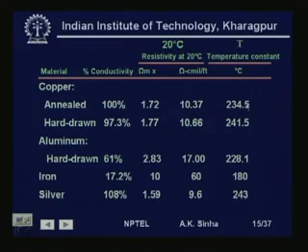As I said, this table shows the temperature constant values. If we look at this table, which also provides the conductivity, annealed copper has been put as 100% conductivity. Then the hard drawn aluminum, which is used for conductors, has 61% conductivity as compared to annealed copper. For finding out the DC resistance of the conductor at different temperatures, we use this temperature constant T.